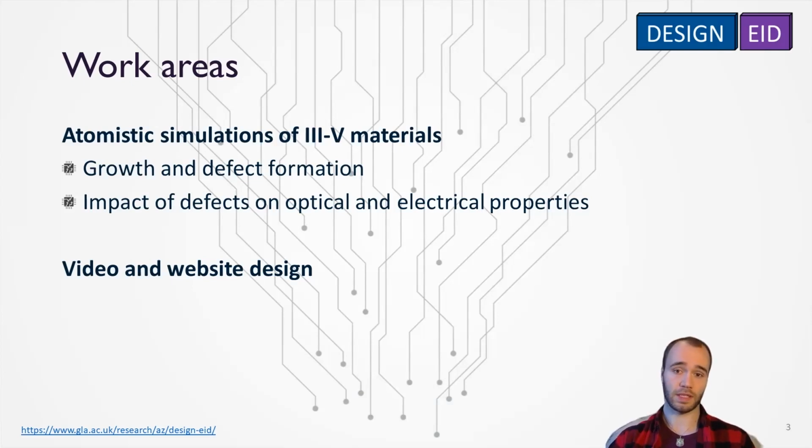The first of these is the growth of the III-V semiconductors, with an emphasis on the defect formation dynamics. The goal is to mitigate their formation, or maybe even control it for desired material properties. The second key area of my research is what properties these defects give to the material, such as how different types of defects influence things like conductivity and bandgap.